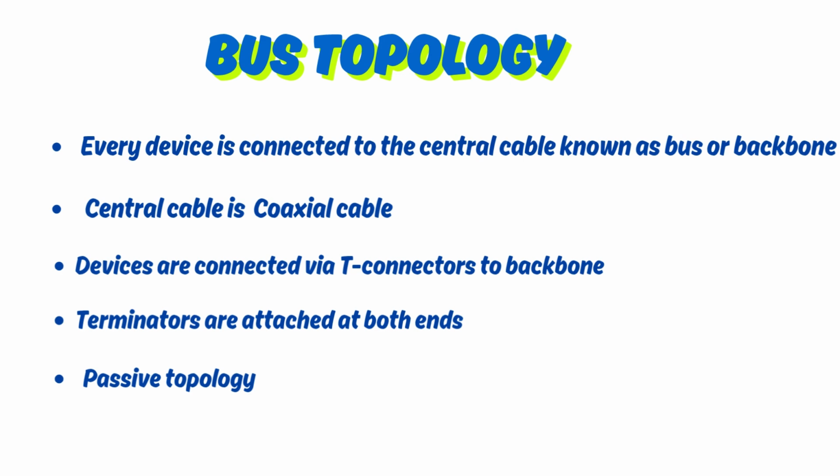Because of this passive nature, the entire network depends heavily on the quality of the cable and the proper termination. If the cable is too long or has a poor connection, the signal can weaken or reflect, and since no device is boosting the signal, the network may fail.